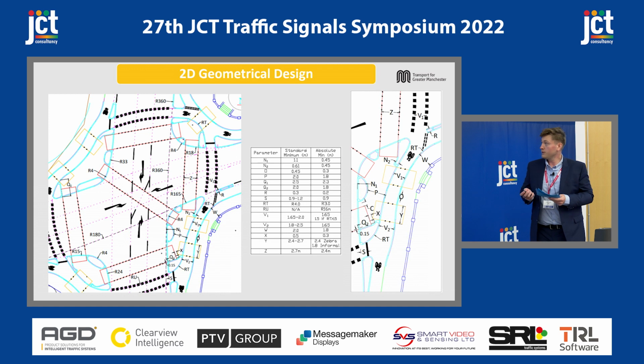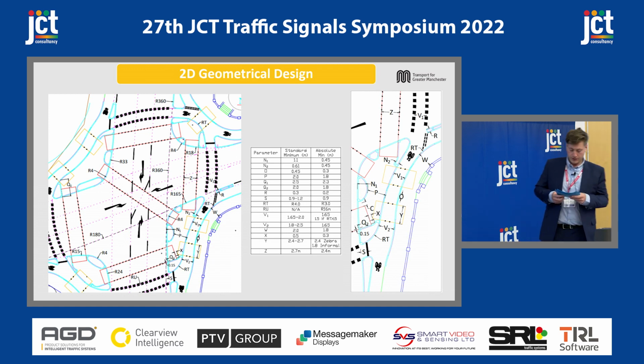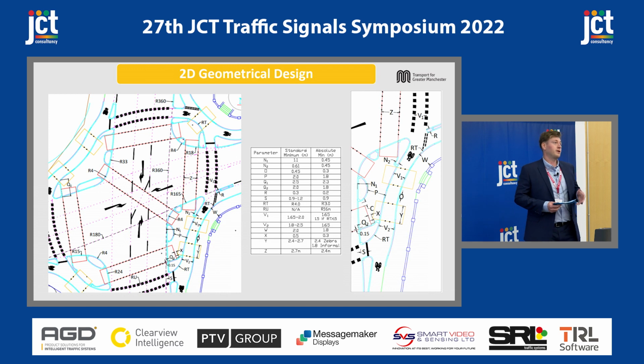So, for example, you've got V1, V2 on the cycle track. So V1 denotes the minimum width of a cycle track on a one-way cycle track, and then V2 specifically denotes the minimum width for a cycle track whereby a cyclist can pass another stationary cyclist that may be waiting at the stop line. We're also due to release a full CYCLOPS technical design guide, and this will feature more standard details to cover a multitude of possible scenarios associated with CYCLOPS junction designs. We also welcome your feedback on these standard details.